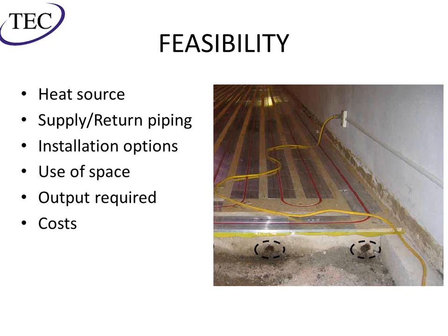Even if you're installing radiant in other portions of the house, you might find a zone, like a distant bathroom on the third floor, where it would just make sense to throw an electric mat in there instead of running piping and an installation. So just stand back and examine the feasibility of the system before you start.